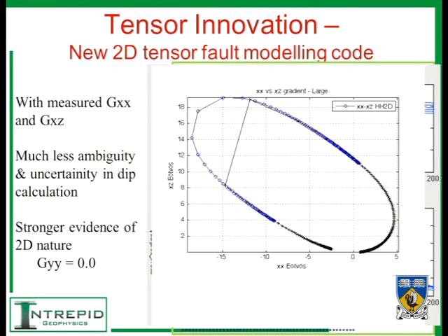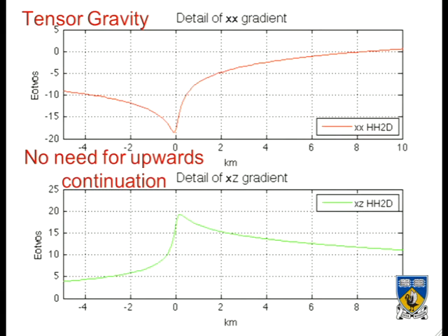And this is the theory, and this is a wonderful starting point for a poor man's inversion algorithm to directly deduce the dip of the faults when you have gravity gradiometry. And they're the components again. There's a trend line with a sort of deviation as you go directly over the fault, and that's there as well.